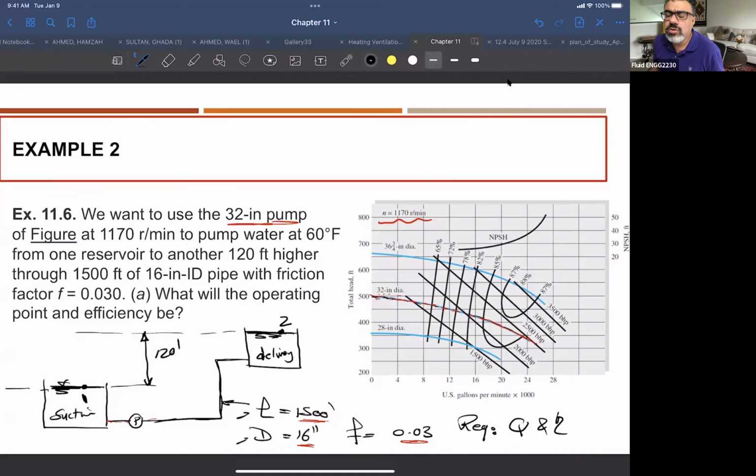To open tanks, no, not really. Trevor, you have to really think about energy at point 1 and energy at point 2, right? In the general case, like we represent in most of these problems, a tank here and a tank there, but it doesn't mean it has to be a tank, right? It could be a point that has pressure and velocity and Z, right? So you are considering this total energy as your first level of energy, okay? Normally, when we are putting a tank here, it doesn't mean it is really a tank, right? But in many applications, we have a reservoir that is carrying fluid from one point to another point.